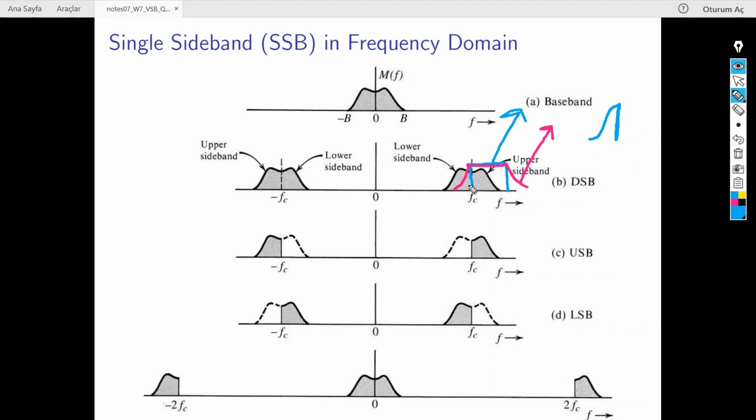Yes, everybody got this point? It is a very critical, important point to understand why we need to use vestigial sideband sometimes, and where we use single sideband. If you are telling us that single sideband requires an ideal filter in order to practically cut the signal as sharp as you can see in the figure, but there are no sharp filters with exactly perpendicular edges, so do we really use single sideband? I tell you, yes, we use single sideband for the audio.